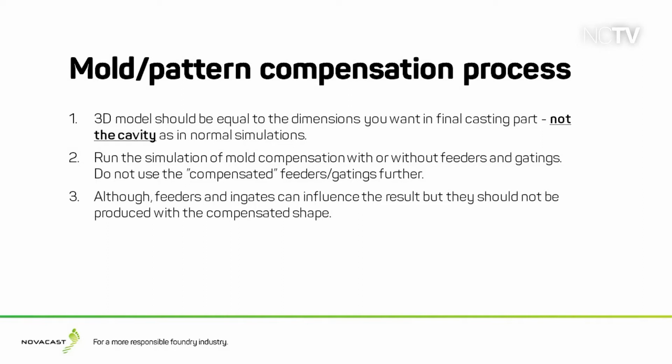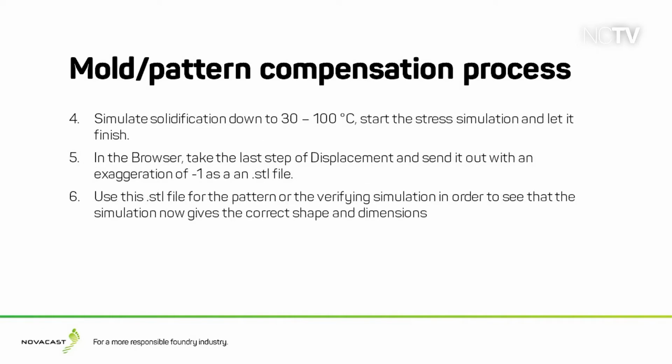You run the simulation of mold compensation with or without feeders and gatings, but the feeders should not be compensated. They can of course be run with the compensation, but it's not something that should be used later on. They can influence the result, but they are not of interest for the compensated shape at all. Then we have the simulation of solidification down to 50 to 100 degrees, or as near room temperature as possible. And then you start the stress simulation and let it finish.